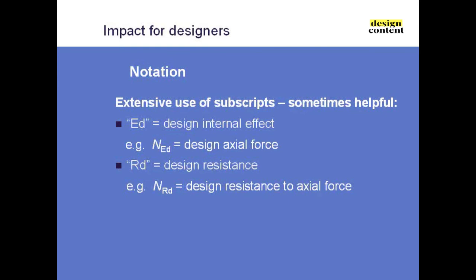And similarly, RD stands for resistance design. So if you see NRD, it's the design resistance to axial force. We'll pick this up as we go through, but basically the D, design, means it's been factored by load factors. So if it's a design axial force, the D means it's been factored by the gamma, the loading gamma factor. If you see a design resistance, then it basically has been divided by a material resistance factor.